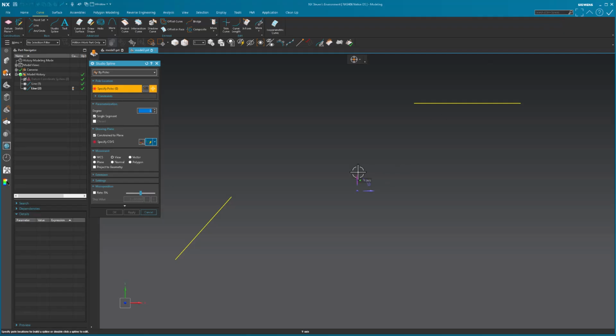So the same concept is true in CAD. There's no difference. It's just the interface is different. A lot of people have a disconnect between the real world and what happens in, we'll call it, the digital world. Okay, so if I want to make a spline, let me go back in here and turn this on, and I pick that point. I just said that I want the endpoint of my spline to go right to that point.